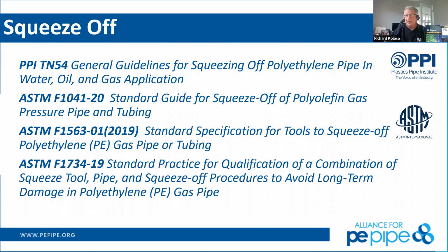If your pipe is big enough, and you've got it in there, and you can camera that line, you will be able to see that deformation. So if it only deformed in one area, which is usually the thinnest part, then you'll be able to see those other areas where it deformed, and you can make a better decision based on what you see in that pipeline. So there are things to do.